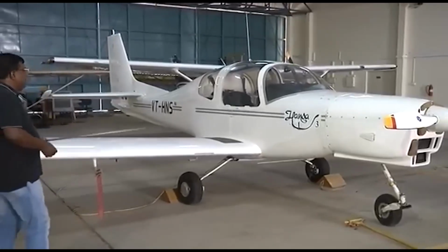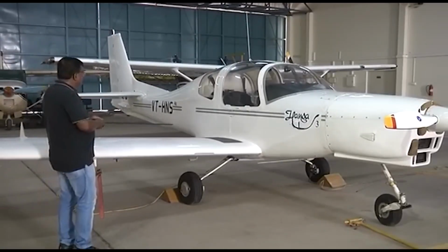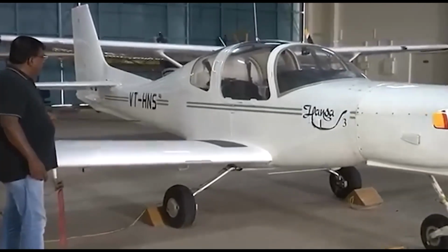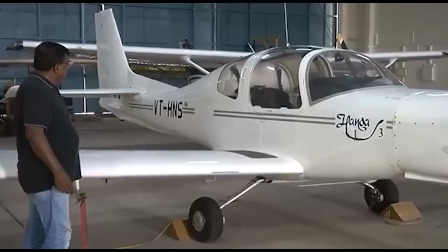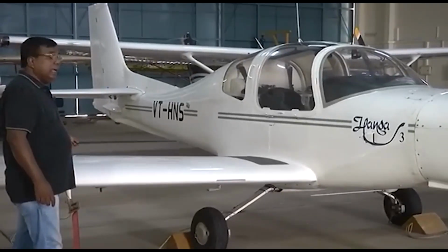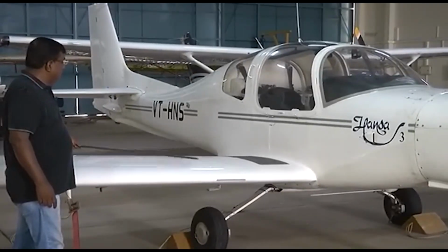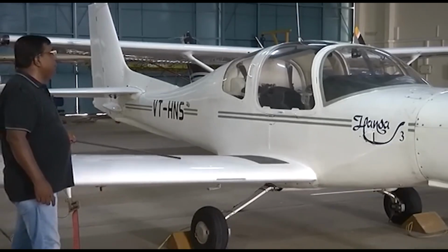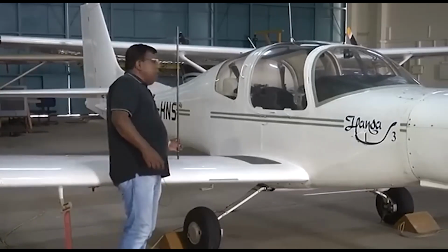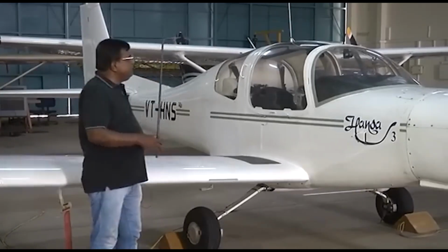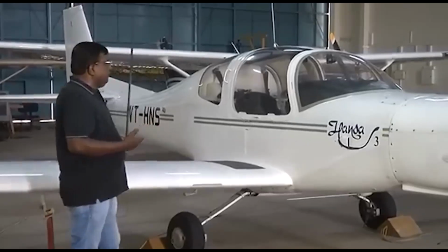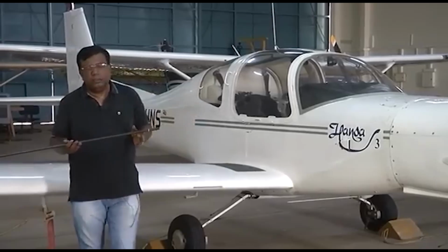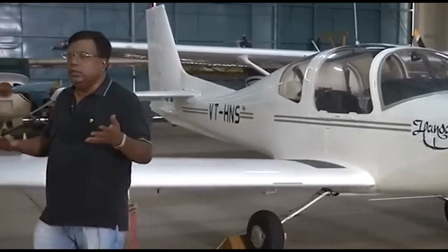Right? Before I stop discussion on this, please also understand we have also shown you that over the wing, if I try to represent where the lift or CL will act, I know that it should be at the quarter chord point. That is, I take this chord and act 25% from leading edge. So I'll say this is my CL, location is here. Okay? So these are the things which need to be kept in mind. Similar thing will happen on the other side, and we will define something called mean aerodynamic chord. We will see as we develop this course.